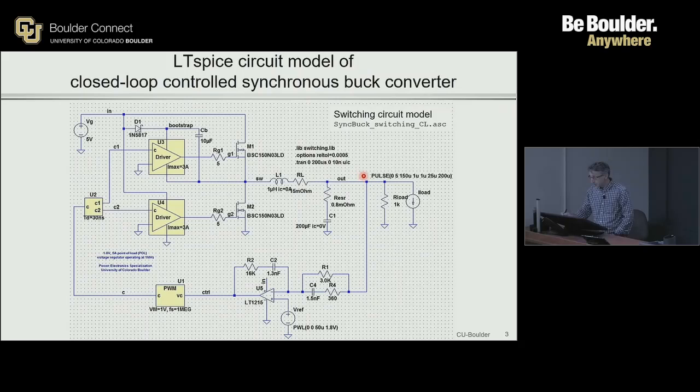At the output of the converter, we have sensing of the output voltage. The sensed output voltage is compared to a reference. The reference here is shown simply as an independent voltage source. In reality, you can go deeper into modeling the reference itself, which would typically be implemented using band gap techniques. If you take an analog IC design class, you will learn how to do that.